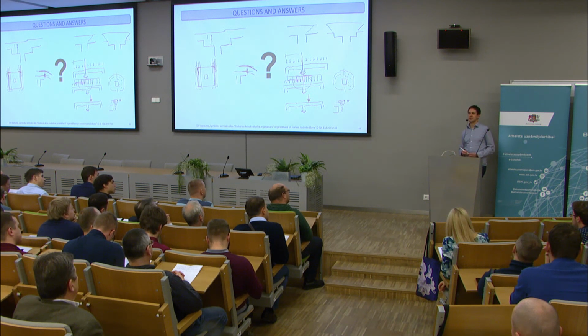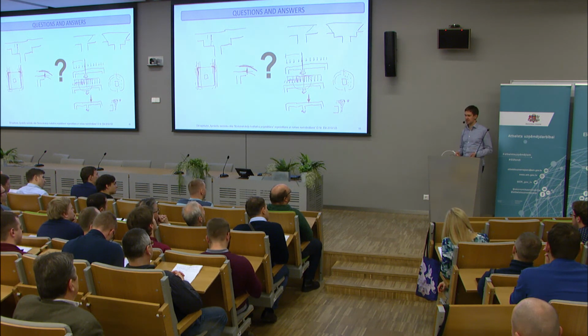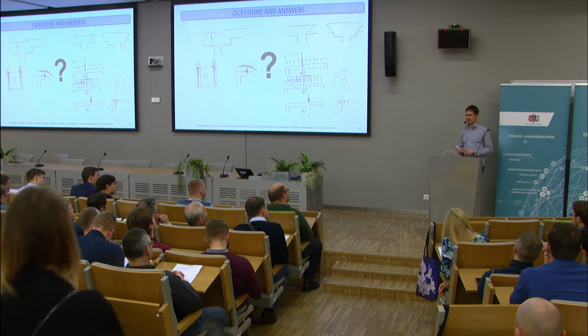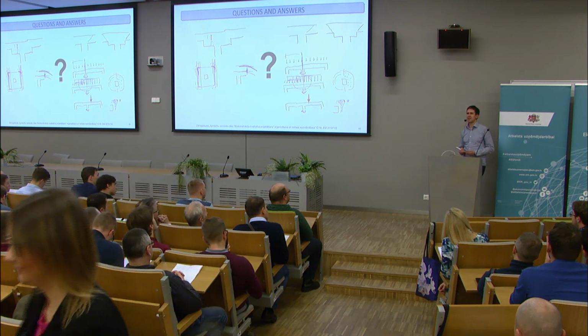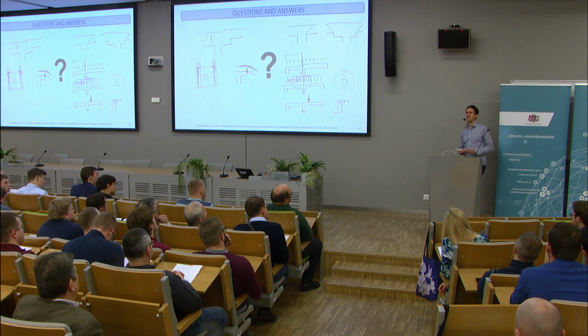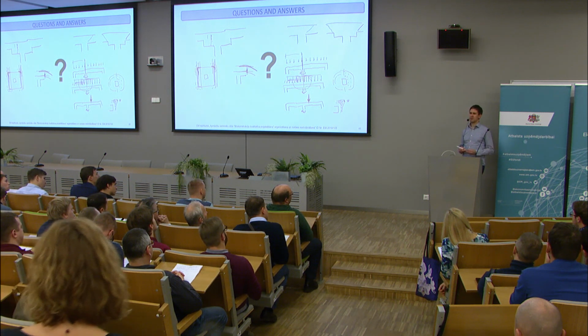Well, with the strip method, we neglect torsion. With FEM design, you get torsional moments as well. So from that point of view, FEM design would actually use more reinforcement because you have to put extra reinforcement to withstand the torsion. But FEM design or linear elastic design is actually also a lower bound method.